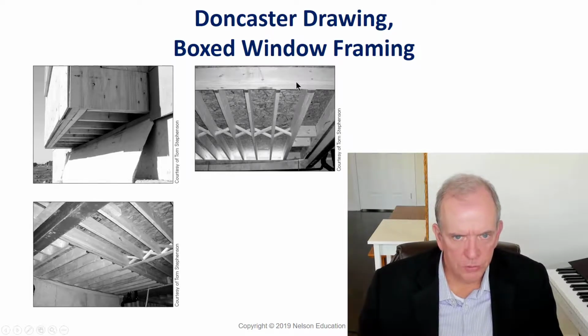So here this is the triple joist, 3 plies. So remember I said how many plies? 3 plies, triple joist, same thing. All right. And the joists are going out and they're cantilevered out past here. There's the double joist on the end. And you can see that they're on hangers. So it's flush, right? So the whole floor system is flush.